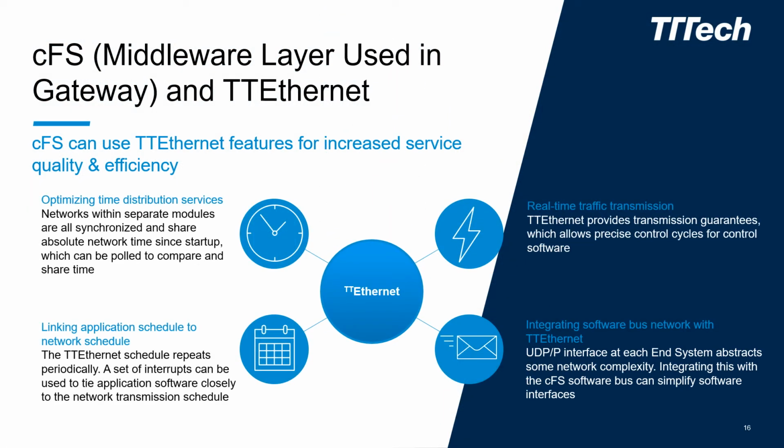Let's have a quick look at CFS, the Core Flight Software, which is utilized on the Gateway. It is enhanced through features that TT Ethernet offers. First of all, time distribution, making sure all participants in the network are synchronized at the same time, and then allowing, once the synchronization is established, to link the application schedules to the network schedule.